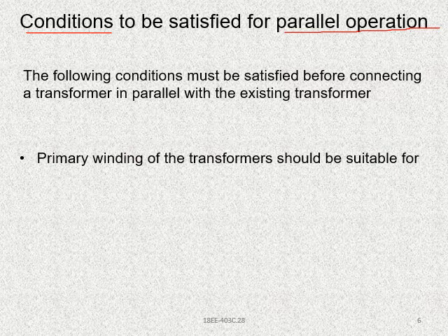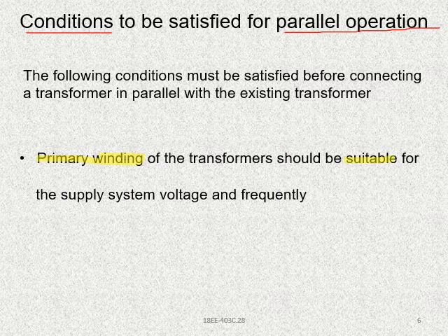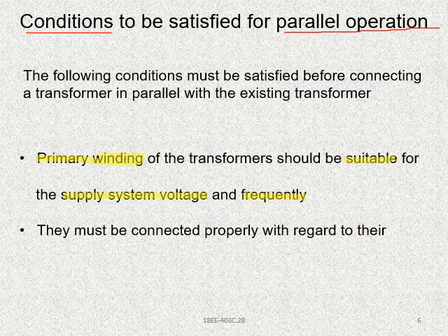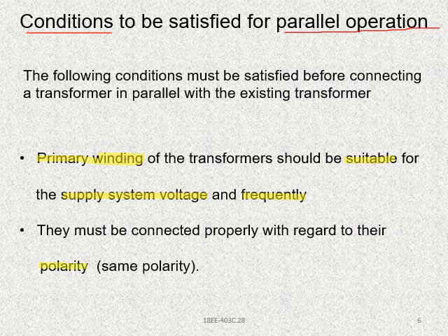First, the primary winding of the transformer should be suitable for the supply system voltage and frequency, and they must be connected properly with regard to their polarity, nothing but same polarity. These are two points over here, and some more points are there in the next slide.